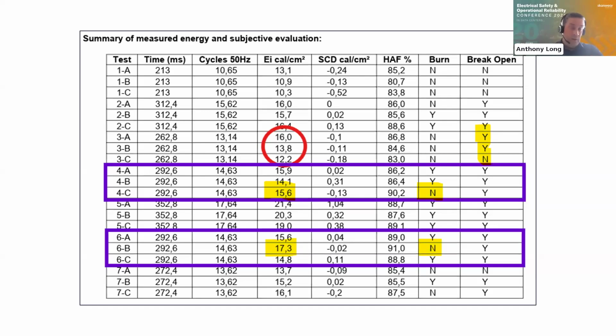So because of that 50% probability, that rings true from the chart you see here now, and the previous charts you see on the same fabric, we get different arc ratings. So this is where we don't believe ELIM is a valid point. Plus, when you move up the scale in terms of protection, it also means you more than double the weight of the garments. So if you have a 12 cal ELIM garment, that would be a lot heavier than a 12 cal ATPV garment. And then when you get to 40 cal, it's near double the weight. So ELIM is really restrictive, really limiting. ATPV or EBT is the best option to get a realistic understanding of the protection of the fabric itself.